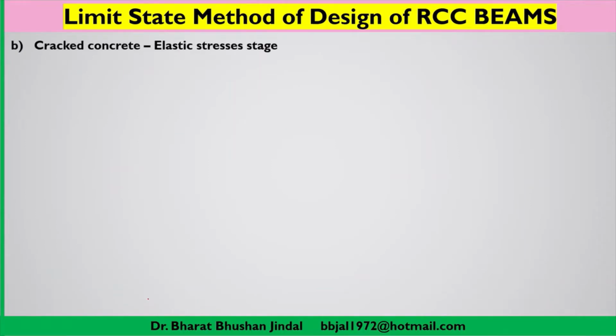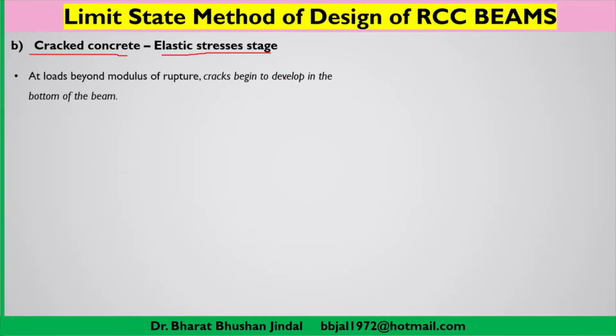Now, the second type of section behavior is the cracked concrete, elastic stress range, within the elastic limit. As we increase the load beyond the modulus of rupture, what will happen? Cracks will begin to develop in the bottom of the beam, meaning below the neutral axis.